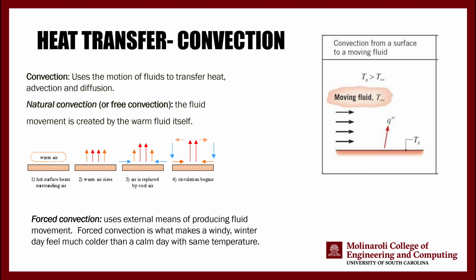But if you put a fan in front of a heater, which essentially forces a fluid flow, if you have an external pressure differential causing the movement of the fluid, you are going to have forced convection. So the difference between free and forced convection is that in one of them, movement is done by a fan. In the other one, movement of the gas or liquid is done because of the warming up of the liquid or gas that is closer to your hot surface.